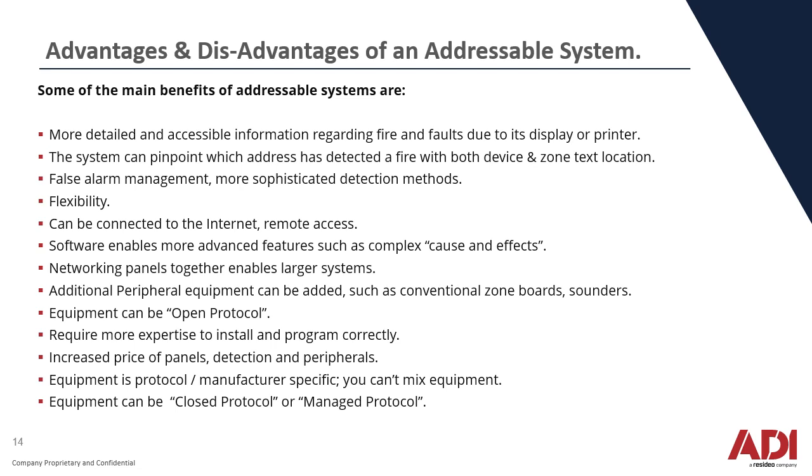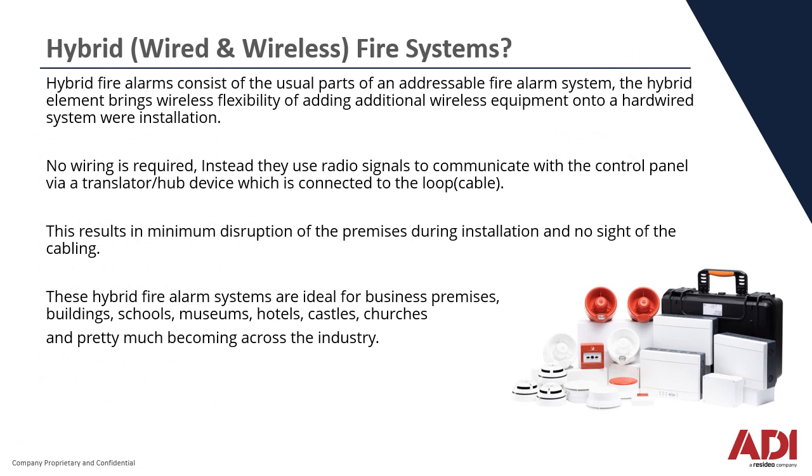Some of the disadvantages of addressable systems are: they require more expertise to install and program correctly, and there is increased price of panels, detection and peripherals. Equipment is protocol and manufacturer specific. You can't mix equipment. Next, we have hybrid fire systems.